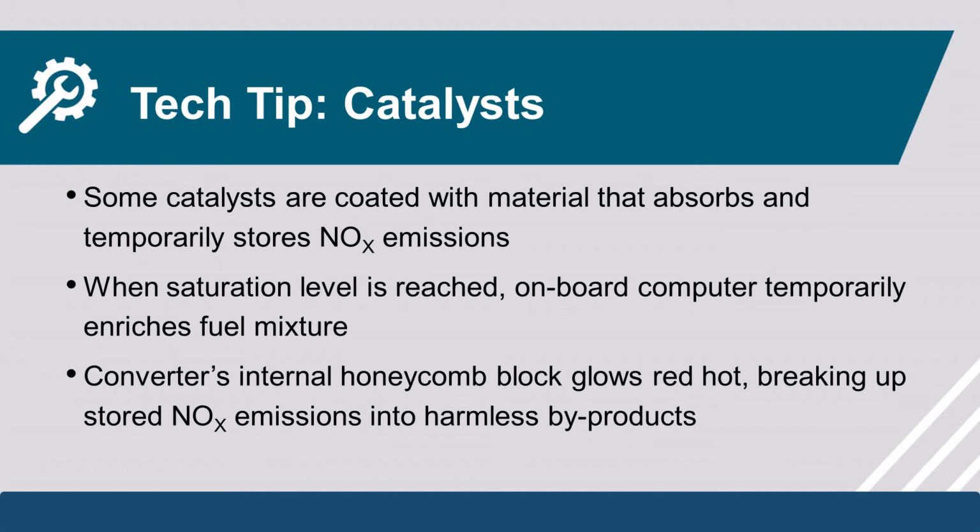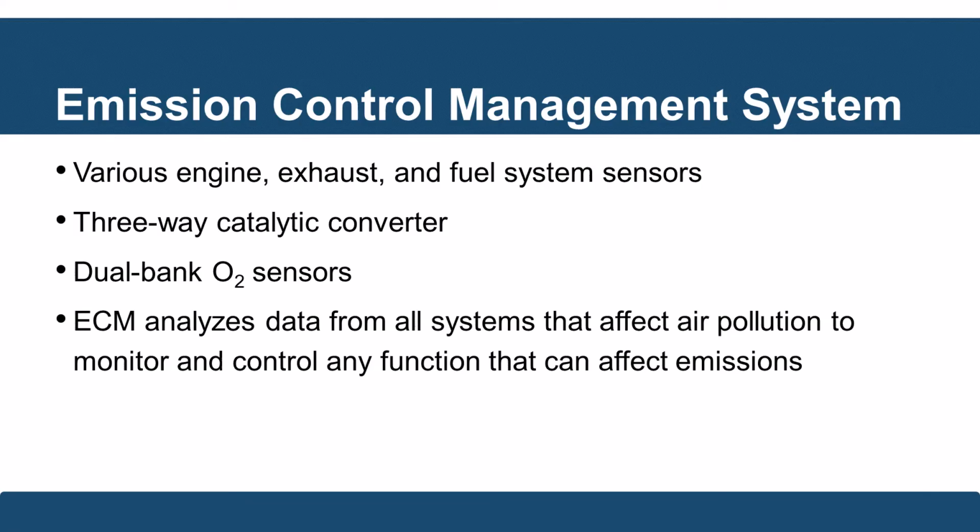A couple of tips to know about catalysts in particular is that some are coated with materials that absorb and temporarily store NOx emissions. And then when the saturation level is reached, the onboard computer temporarily will enrich the fuel, which allows the converter's internal honeycomb structure to glow red hot, breaking up the stored NOx emissions into harmless byproducts. This goes on quite a bit. We'll learn more about that with diesels as well. There's a system.